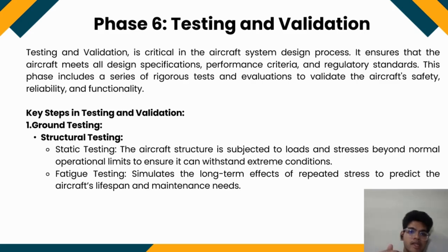In ground testing, we start with structural testing, which includes both static and fatigue tests. Static testing involves subjecting the aircraft structure to loads and stresses beyond normal operation limits to ensure that it can withstand extreme conditions. For example, we apply forces to the wings and fuselage to simulate scenarios like severe turbulence or emergency maneuvers.